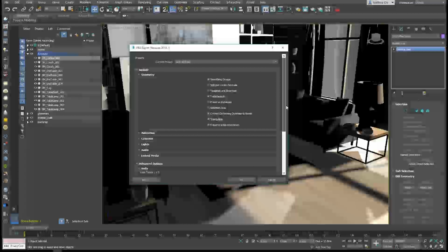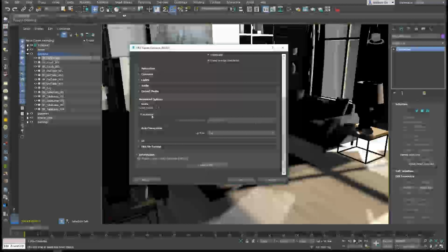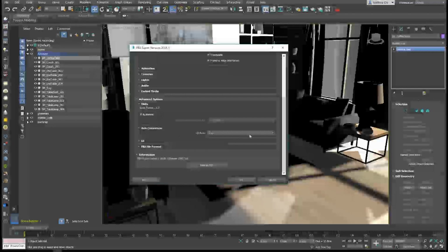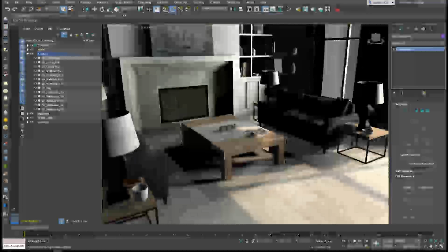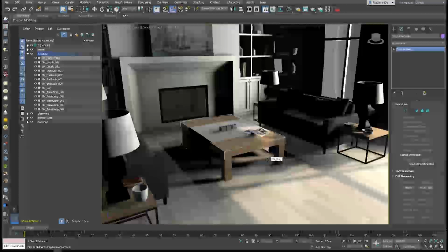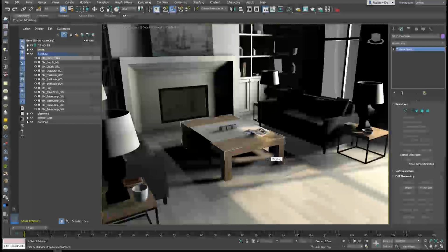So again, just to recap, we want to use smoothing groups. We want to triangulate. If we're using cameras and lights, we want to turn those on. And then finally, automatic scaling set to centimeters and Z up for our axis. All right, and now we're not going to actually jump over into Unreal to show the import process. We're going to do that in the next video. Let's just go ahead and look at Datasmith now.